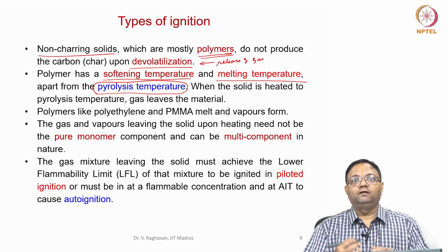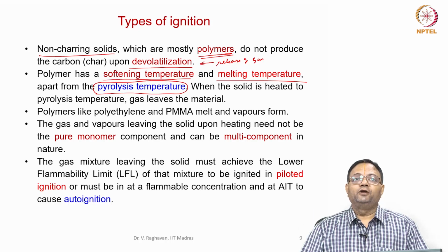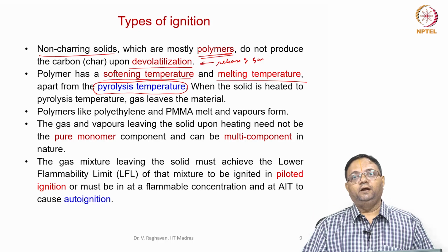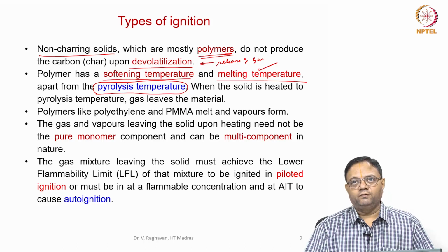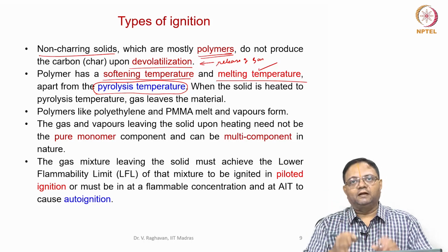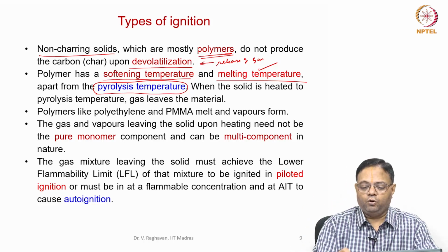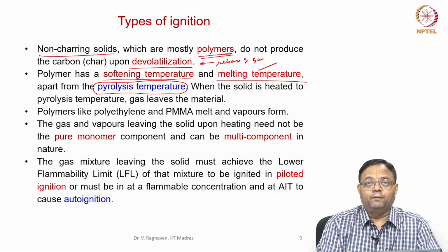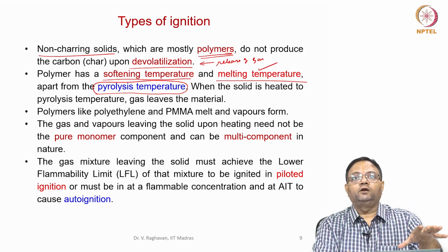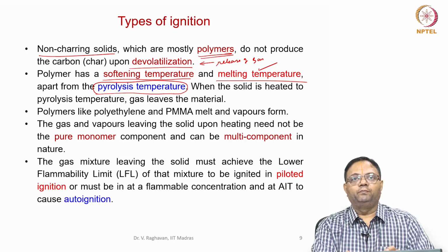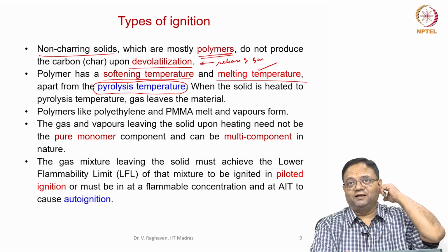Now this gas release can be due to direct sublimation, solid straight away to vapors, or it can be first melting, forming a liquid surface or thin film of liquid, which then will vaporize. So the pyrolysis temperature can be close to the boiling point when a melt is formed, or the pyrolysis temperature can be the sublimation temperature when there is direct sublimation.